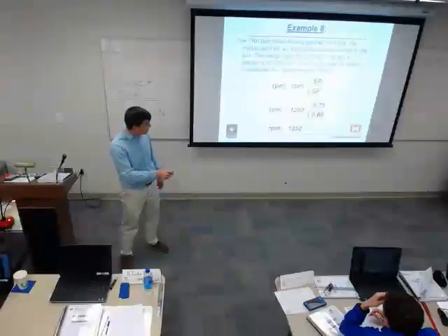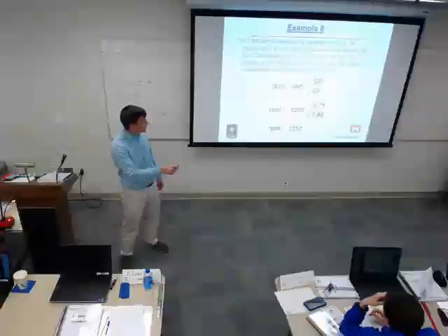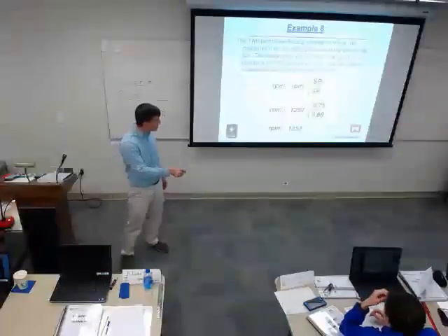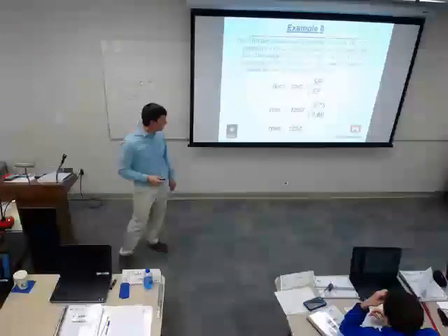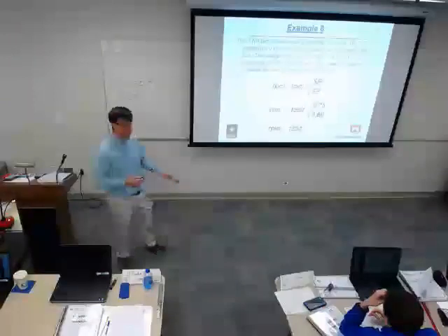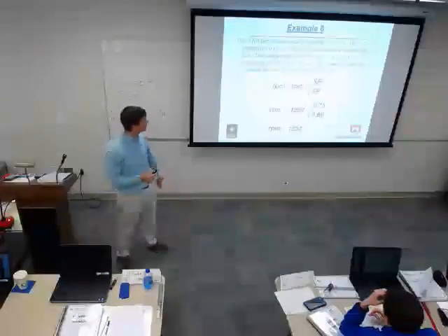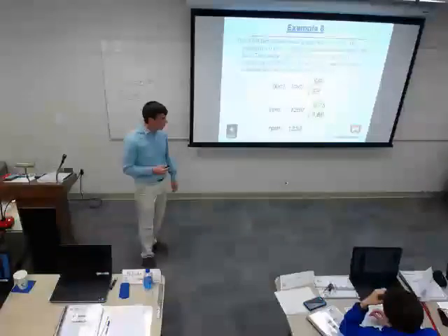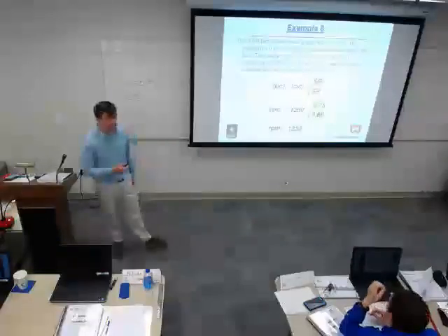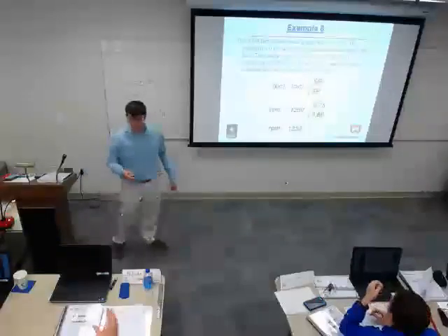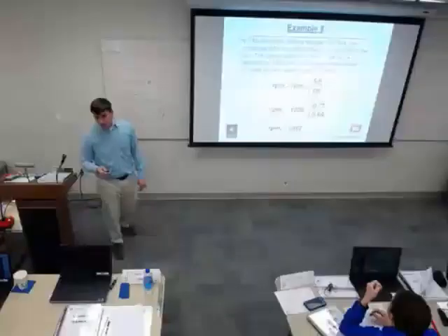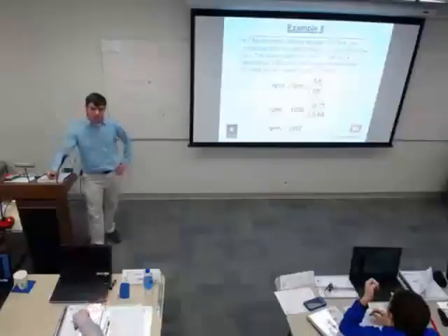I measured 1250, that was RPM 1. I was given that I needed to get to 0.75, plugging those numbers in. There's a corresponding change in RPM I'd have to make to meet that static pressure. The point being, you can rearrange those terms to figure out where you need to be. Before you do all this though, you need to back check everything leading up to it.